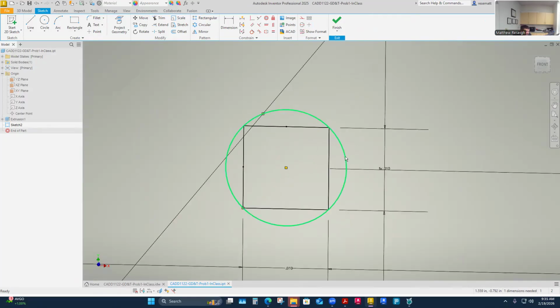So this isn't necessarily the size of my true tolerance, because for whatever engineering standard had been developed, they decided those holes can be toleranced to 0.025 thousandths, which will be sufficient to make the fasteners or hardware fit up, or the way this bolts to something else. So they actually gave us more tolerance than just the applied one. So I'm going to delete this. They gave us more tolerance.